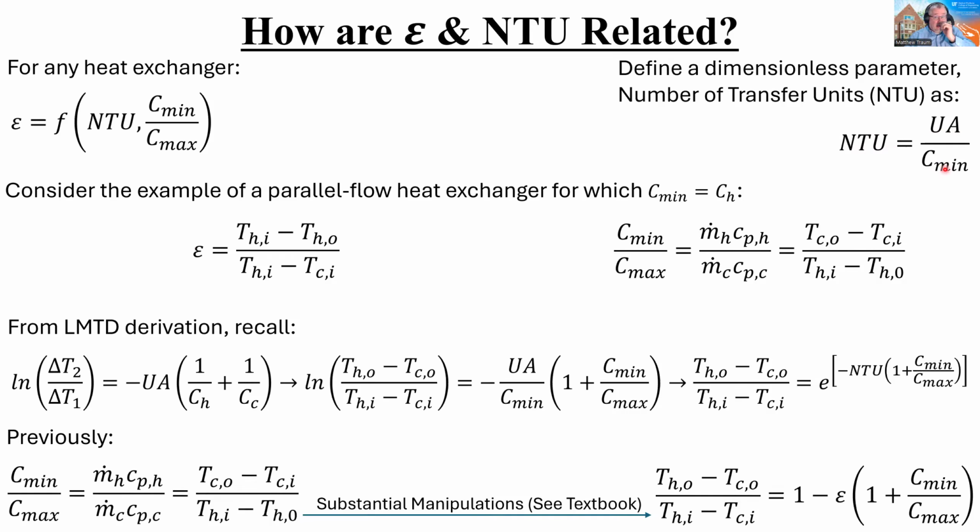And then just kind of non-dimensionalized. I should mention that too. It's dimensionless, so we're just non-dimensionalizing by the thermal capacity of the stream that has the lower of the two thermal capacities. And so what we need is some functional relationship between NTU and the thermal capacities of my streams. So just a ratio of those, and that gets us to effectiveness. So what is that functional relationship? Okay, so it is different for every heat exchanger configuration, which is what makes this technique a little bit cumbersome.